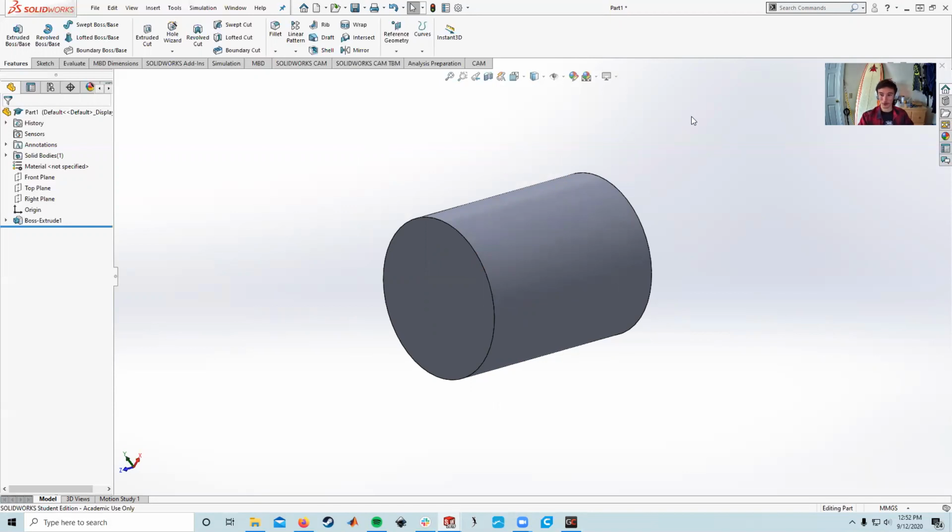And as with most tools in SolidWorks, when you create a feature, you're going to need the sketch that you're going to bring into the third dimension, and then you need some geometric reference that tells SolidWorks what to do with that sketch. So I haven't made the sketch yet, but in the case of the Revolve tool, you need to add an axis that your sketch is going to revolve around in the future. So I'm going to do that really quickly.